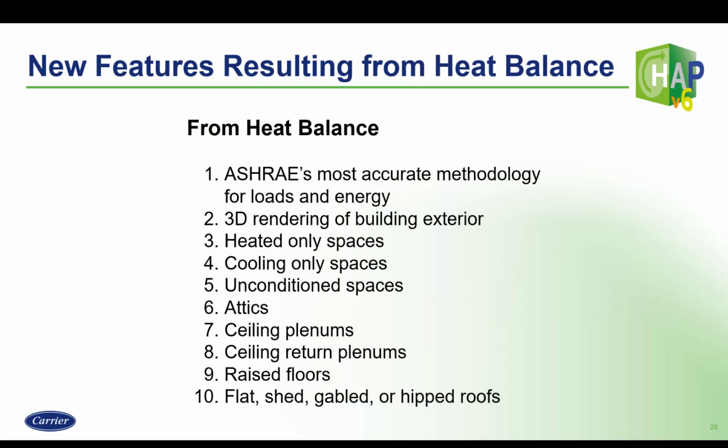There are quite a few additional applications in HAP version 6 resulting from heat balance. We have already discussed numbers 1 and 2 as shown here. Additional ones are heated-only spaces, cooling-only spaces, unconditioned spaces, attic temperatures, ceiling plenums, ceiling return plenums, raised floors, and finally flat or shed or gabled or hipped roof modeling. Remember we said earlier heat balance increases the range of applications?